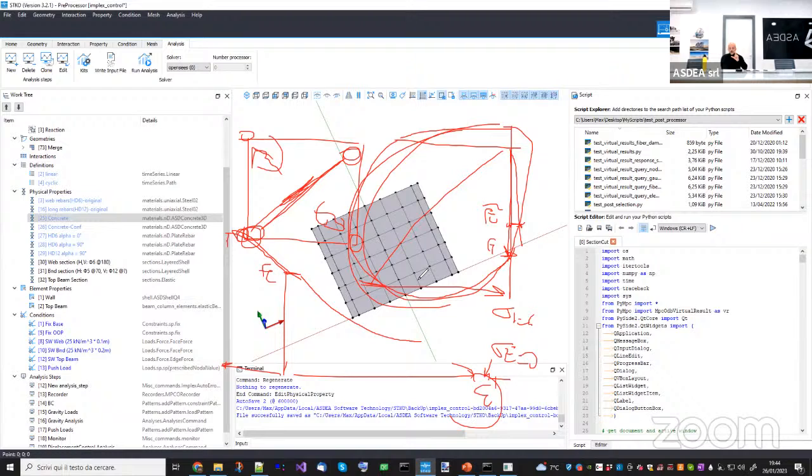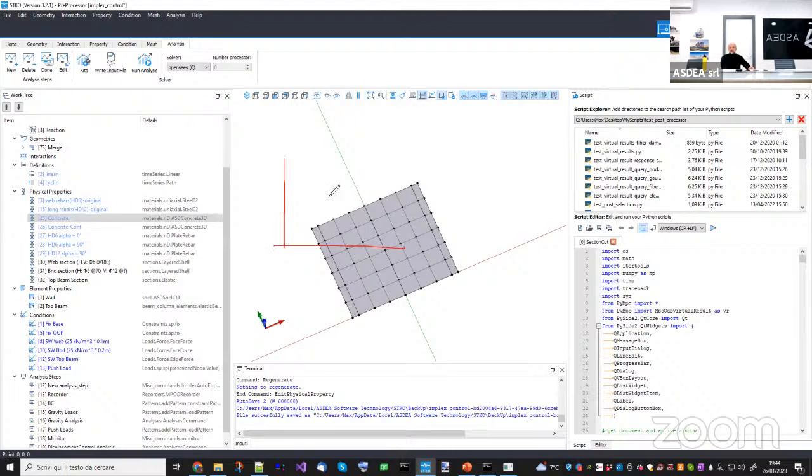Instead, the reason why we added the directionality of the internal variables was because this was something that we saw on the beam truss model. So the concept was the beam truss model is a collection of trusses like these, for example, for the vertical cracks, and then for the shear cracks. Now, this strut here communicates with these points just to get the strain on the orthogonal direction, but it doesn't communicate with any other truss element. So basically, if I have a crack here due to the tensile opening in this direction, this one does not affect what's going on in shear.